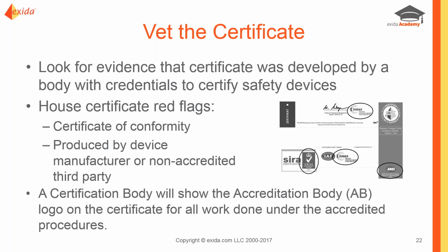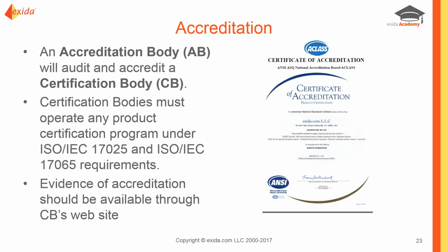And certainly if it's not there, you would encourage the certification body should also have evidence of their accreditation certificates on their website. And they need to be certified under the ISO IEC 17025 and the ISO IEC 17065 requirements for doing SIL certification, or doing devices that are going to be used in SIL certification. So definitely go out and look at the certificates you're receiving. You want to go out and do this scrubbing and locate the accreditation body, and your plan and procedures ought to have guidelines in there for people to do this.